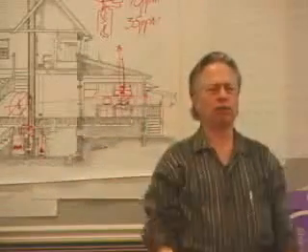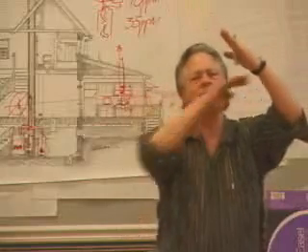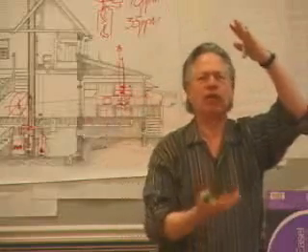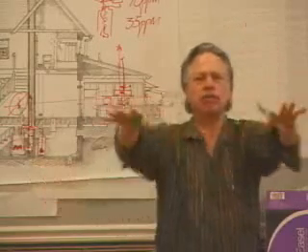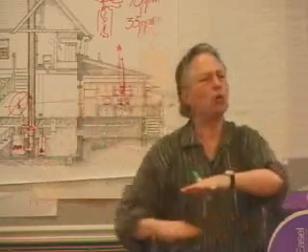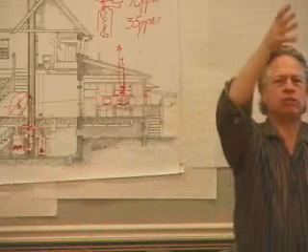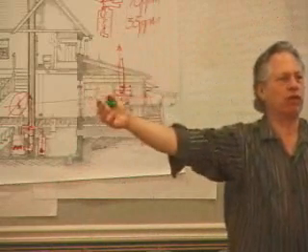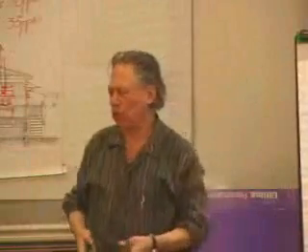The buildings are built sort of like towers, and they have these boards like this, and the prevailing wind blows across it and creates a suction. And it pulls air from the streets. And all the streets are covered with trellises with vegetation, so the streets are all cool. And it pulls air through the streets and up to the houses. Just natural convection currents. It gets warm, the air blows across the house, creates suction, and it's pulling air up. So it's the natural currents.